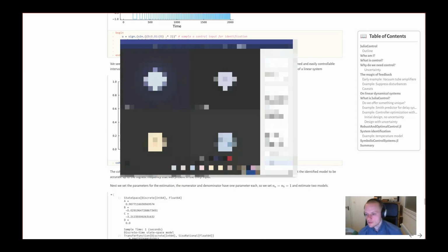So when it comes to the control system identification package, if you have a feedback system, I recommend you make use of the prediction error method. If you make use of subspace identification, at least the methods we have in this package, they will be slightly biased under the influence of feedback, but the prediction error method is unbiased in this case.